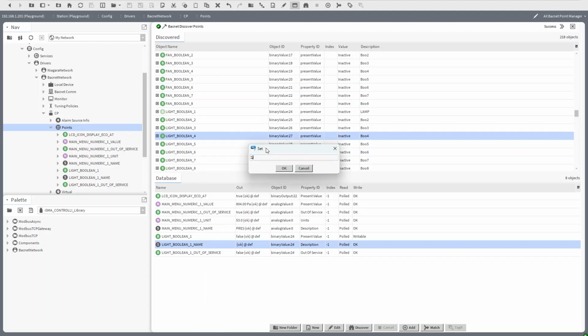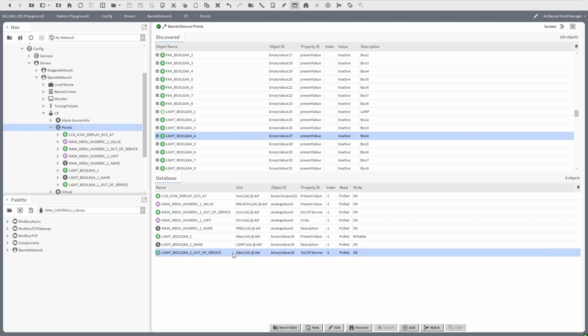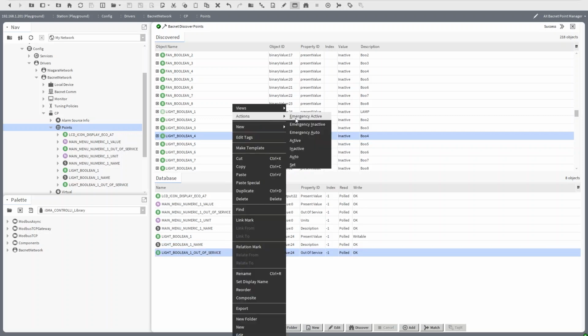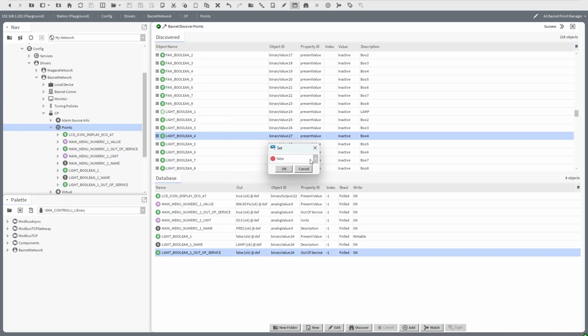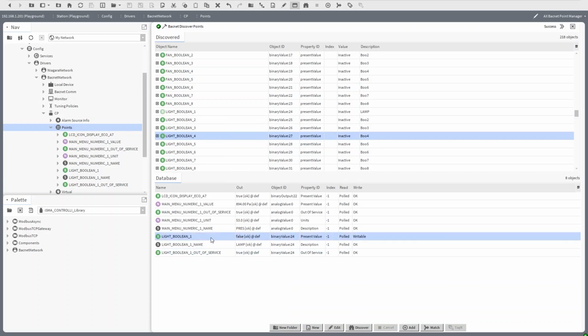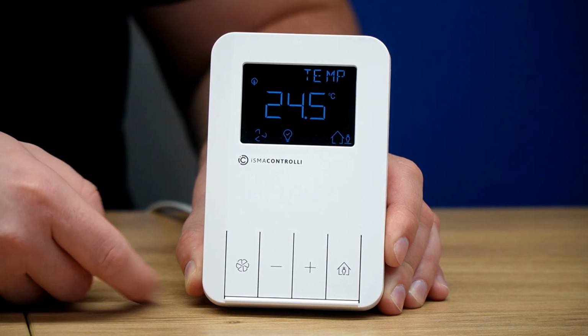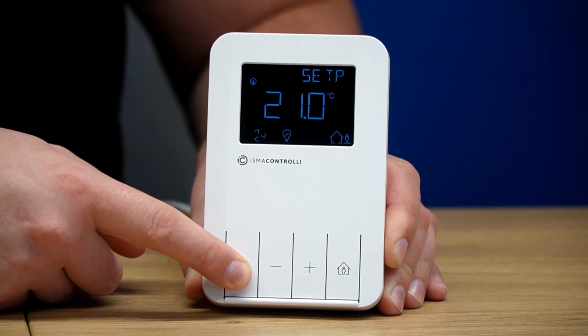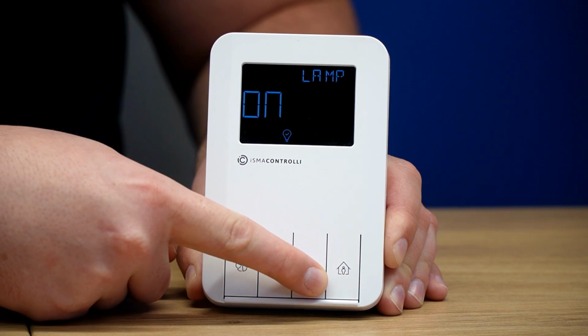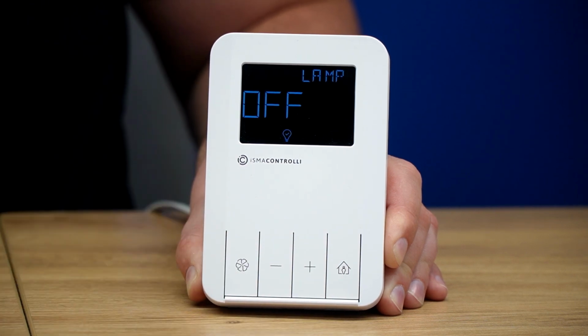To do this, let's use the BACnet Light Boolean 1 object, which allows to display and edit binary values in the light menu. This time, simply enable displaying of this value using the out of service property and add a name in the description property. Everything is ready. By holding down the File button, I can access an additional menu and use the plus and minus buttons to change the light state. This value is available as a value of the Light Boolean 1 object.